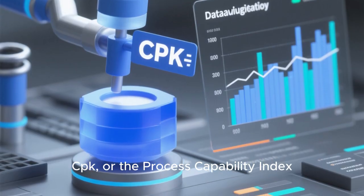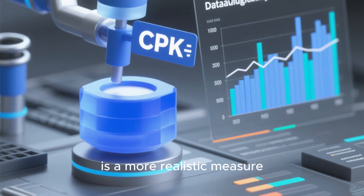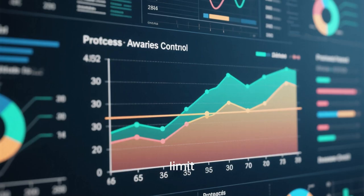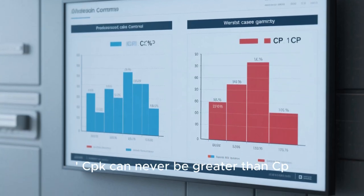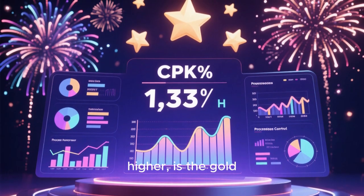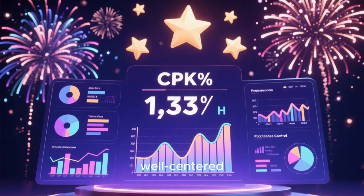CPK, or the Process Capability Index adjusted for centering, is a more realistic measure. It looks at the distance from your process average to the nearest specification limit. Because it considers the worst-case scenario, CPK can never be greater than CP. A high CPK, typically 1.33 or higher, is the gold standard, signifying a process that is both capable and well-centered.